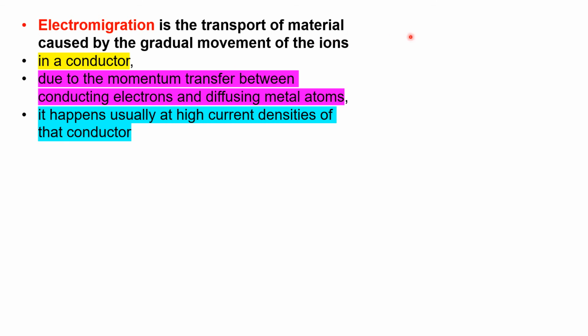So if you observe that, it is definitely understood that electromigration is a serious threat to the long life of ICs. In the worst case, it leads to the eventual loss of one or more connections and intermittent failure of the entire circuit. So we need to avoid these reliability failures. The reliability of interconnects is not only of great interest in the field of space travel and for military purposes, but also in civilian applications like, for example, the anti-lock braking system of cars.